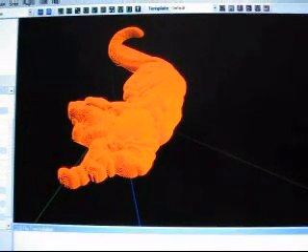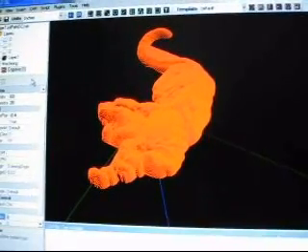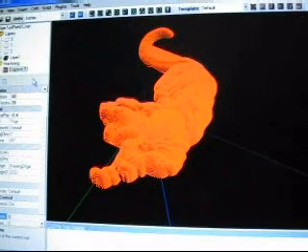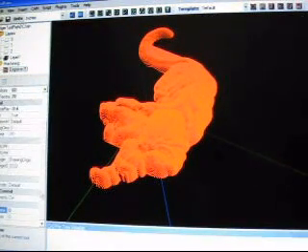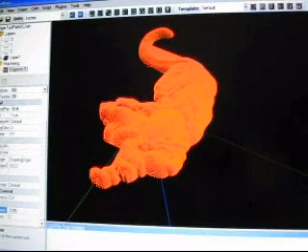It's going to bring up the same menu over here on the left. And let me show you the menu I'm talking about here. I'm into this menu right here, which will give me our parameters. A tool diameter we don't need, we know we're going to run this with an 1/8 inch ball mill. So it doesn't matter. It's just an engraving program. But I'll put it there anyway. So I'll put a 0.125.